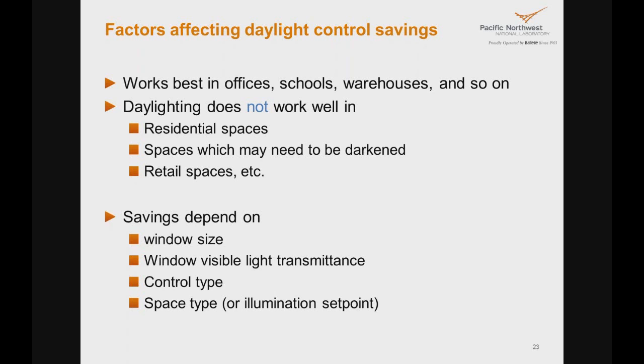Daylighting does not work very well in residential spaces, obviously because there is no one there during the day, and if there is no one there during the day, you might as well turn the lights off, so you don't need daylighting controls to do that. It doesn't work so well in spaces that need to be darkened. For example, in auditoriums, you can work it into a daylighting design, but it's difficult to do, as we saw with that classroom. There are some other spaces in which daylighting doesn't work very well. Retail spaces, for example, is an example.